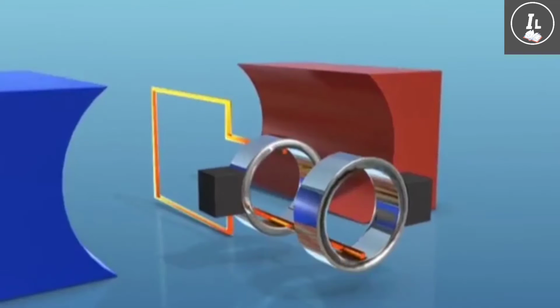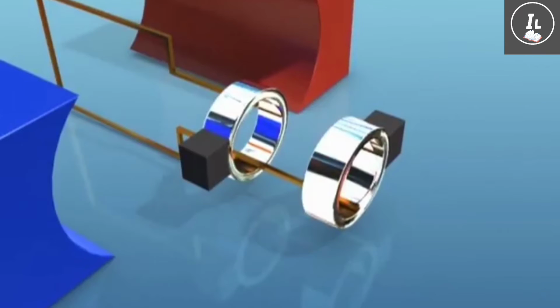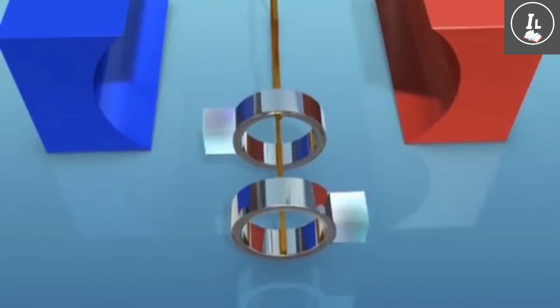Armature is a soft iron core on which a coil having a large number of turns of copper wire is wrapped. The 2 ends of armature are attached with 2 slip rings. These rings rotate with the coil. The slip rings are made of metals and are insulated from each other. 2 brushes are made of carbon.